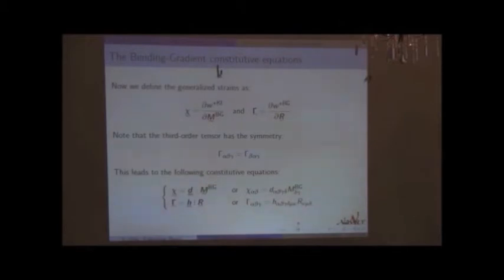So we have the constitutive equation, and now I take the equilibrium equation and its weak form, and I will find the principle of virtual work in the end. I do it with Levi-Civita's notation. Let's start with the classical thing.